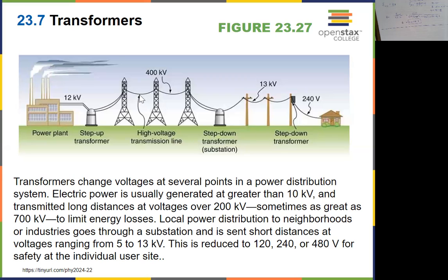because the dissipation is pretty much consumed by the resistance of the transmission lines. The transmission lines have R that is fixed. So if you want to reduce the dissipation, you want to reduce the current while it's being transmitted. So I here should be much smaller.